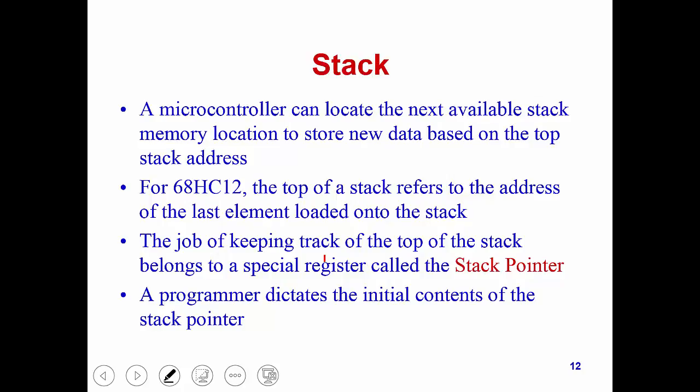Now, we said that the stack is a set of memory locations designed for us to store values. But how can the microcontroller access our stack? A microcontroller can locate the next available stack memory location to store new data based on the top stack address.